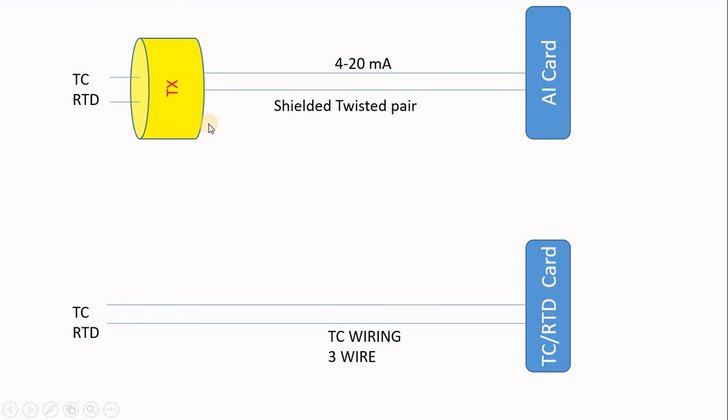A lot of people will go with this solution because it gives you an easy, clean solution, and you can have a standard twisted pair for each one of those transmitters. On top of that, if it is hard to reach, you can reprogram it from the control room. So a lot of the time we go with this solution, but in machines, you can also find that this is a very cost-effective solution.